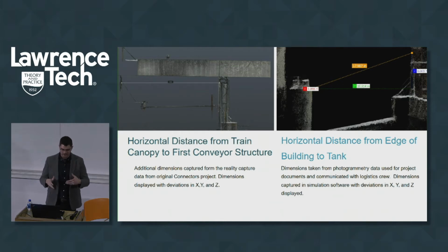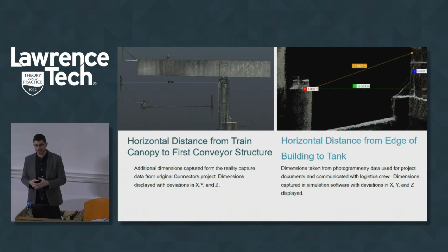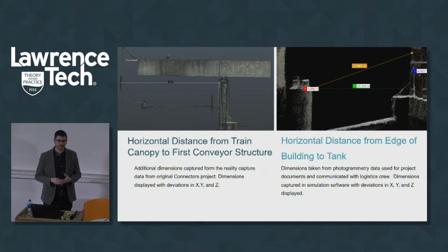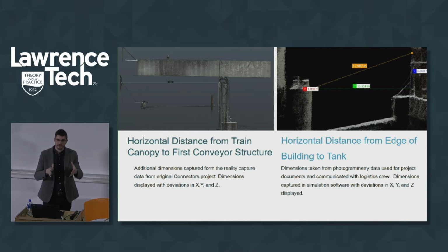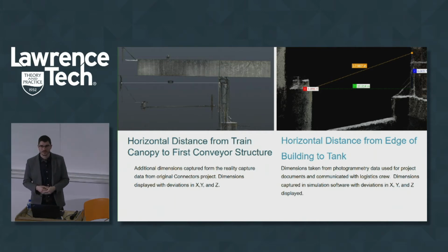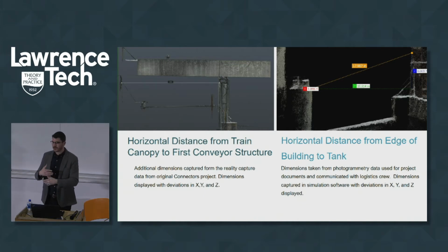But because of all the combinations of tools we could utilize, we were able to really impact the installation method and say, I see what you're saying, installation crew, but we have reason to believe that you're going to be scraping this entrance here off the west. You should consider looking at the east entrance, or you should consider placing your crane a little bit farther back because the tank, when it comes up, is going to be bowing a little bit more than you expected. And we're able to actually take what we've used to design our project and impact the logistics and the schedule of the project.